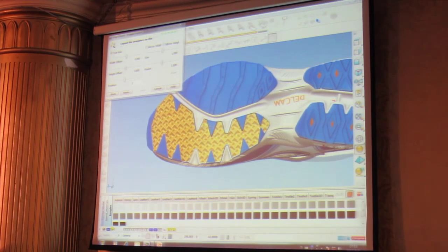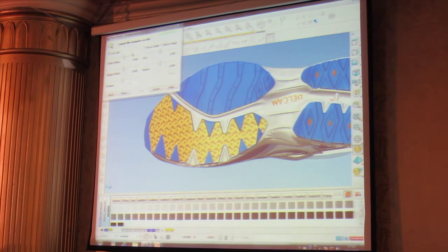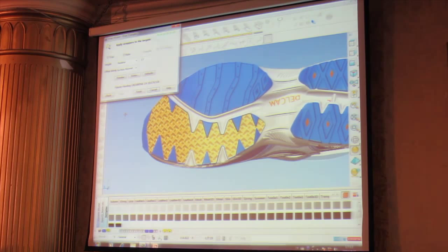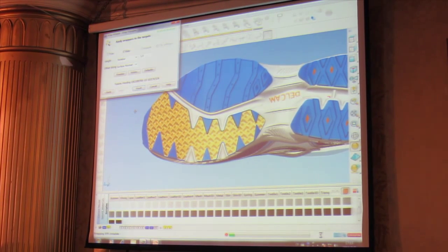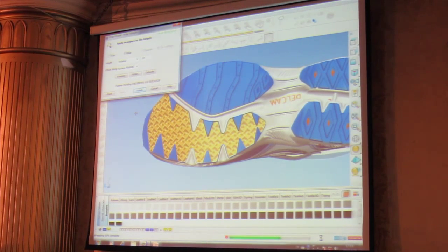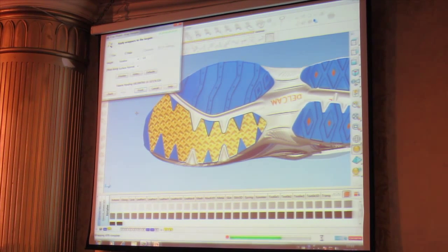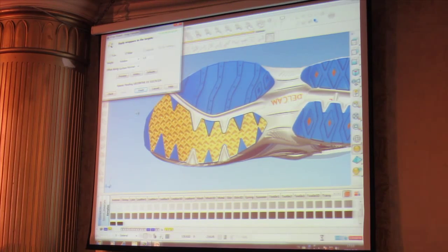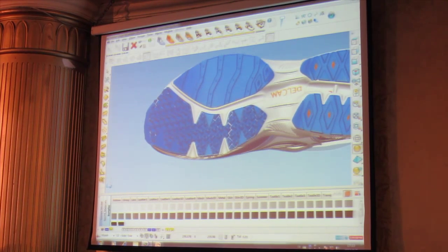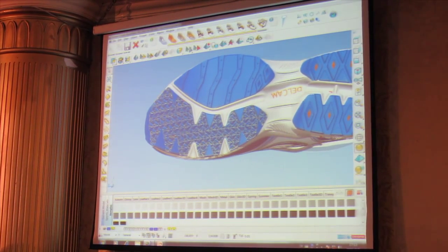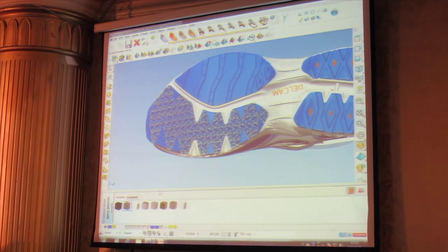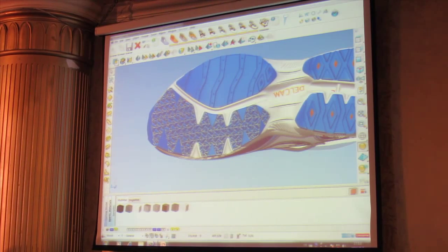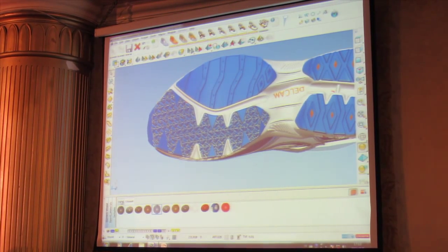So you can see here I've got an angled shoe texture. Here we get the ability to adjust the size and position of the texture, and then finally ShoeMaker will wrap that texture onto the bottom region of the sole. So a bit like the demonstration I gave you with the skate where we created the logo in ArtCam, this is using very similar functionality in ShoeMaker, except in this case we're applying materials or textures to the bottom of the shoe sole.